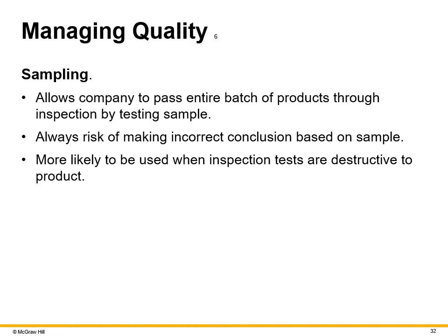When inspection processes are expensive to perform, use elaborate testing equipment, destroy products, or require many hours to complete, it is usually desirable to test just a sample of the outputs. If the sample passes inspection, the inspector may assume that all items from the lot also pass inspection. Sampling will probably be used if tests are destructive to the product. If human lifespan or safety depends on these items, 100% inspection is called for.